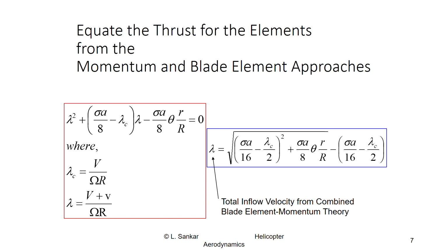That means if you have a rectangular blade and theta varies as 1 over lowercase r, then you get a uniform inflow, which, as we alluded to, will produce the lowest induced power. Such a thing is called the ideal induced power. Therefore, when theta equals some constant over lowercase r, that's called an ideal twist.